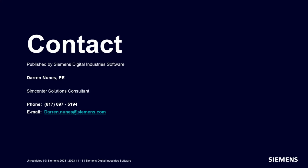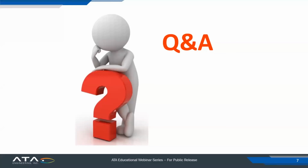Yeah, so that's a great question, and we get it quite a bit in terms of, how do we pre-process the data? How do we look at what types of simulation or design of experiments we're performing prior to being able to import it into a reduced order model? So I wasn't able to show it, but there's a pre-processing functionality. If you have some anomalies in your data, you're looking at it and you have some outliers, you can automatically remove those, otherwise they will skew your training.